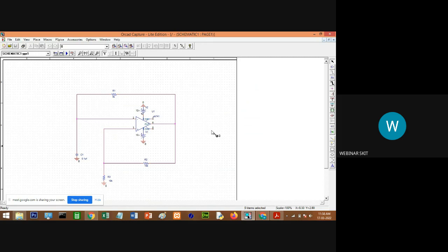Now there are 2 types of waveform we will get through this circuit. One is a square waveform. Okay, another one is the capacitor waveform. If you want to get the capacitor waveform, connect this voltage level marker to pin number 2. See here, pin number 2, we have connected the capacitor. And to get the square waveform, this is connected to pin number 6. To see the output, pin number 6, the square waveform output. End mode. Save it. Okay, then click on run.